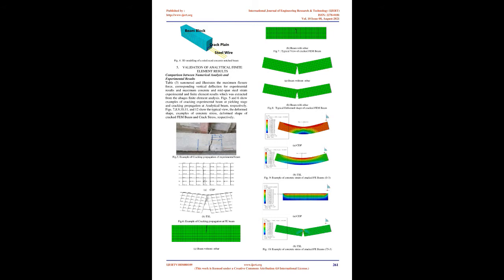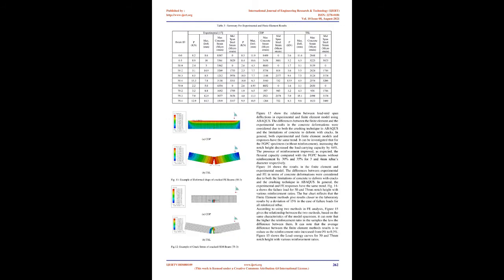The concrete damage plasticity model, CDP. The model indicates that the main failure mechanisms are tensile cracking and compressive crushing of the concrete material, indicated for 47.5 MPa concrete in [23]. The model assumes that the concrete response is governed by damaged plasticity, as shown in Fig. 3, [15] and [24].